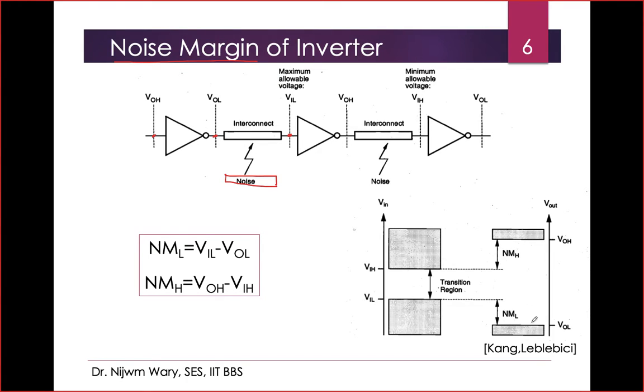Due to coupling of noise, the voltage can even be lower than VOL if the noise is in the opposite direction, but generally it will be VOL. This is the margin.